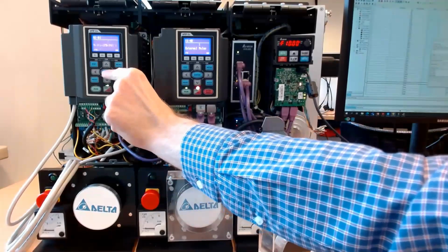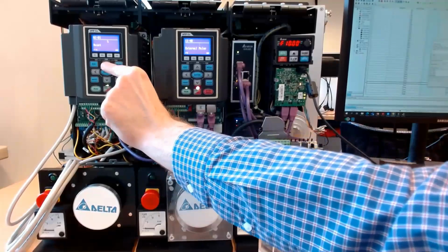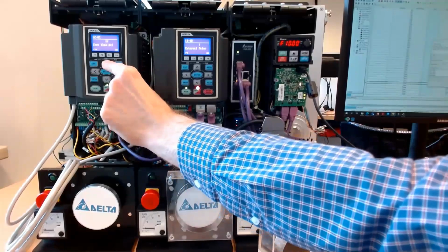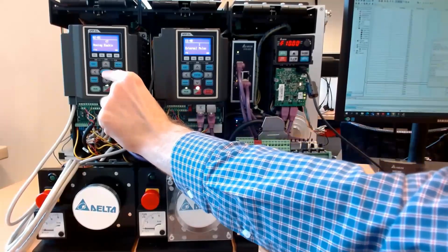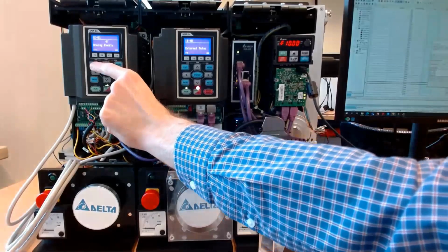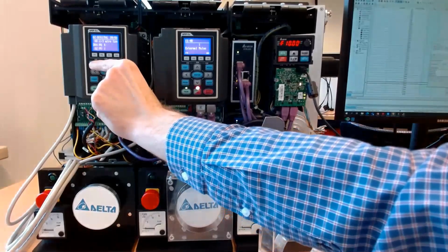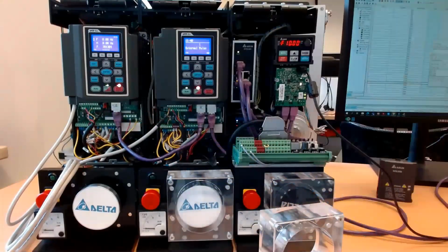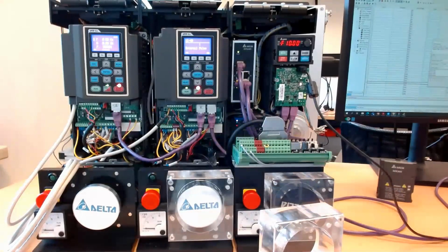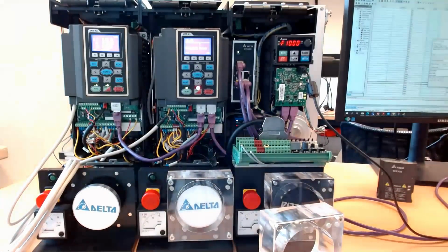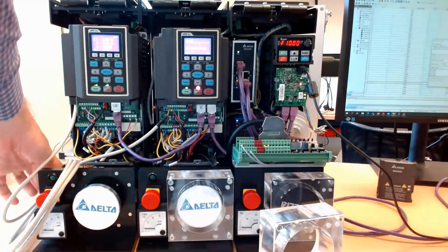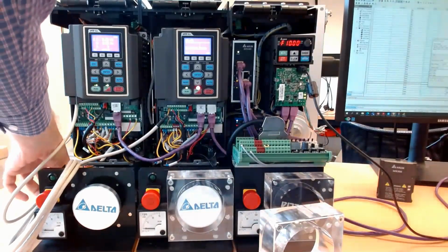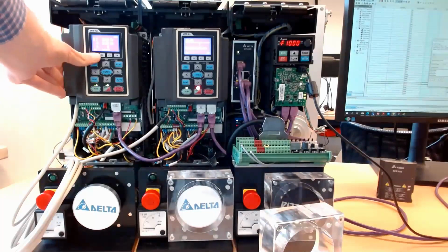And I can also program one digital input to start the homing. So for instance, MI1, if I set this to 47, then this enables homing. When I trigger MI1, you should see the position of the drive switch back to 0. So firstly, I'm going to give it a servo on. And then I have a digital input over here. Yeah, and you can see the position switching to 0.